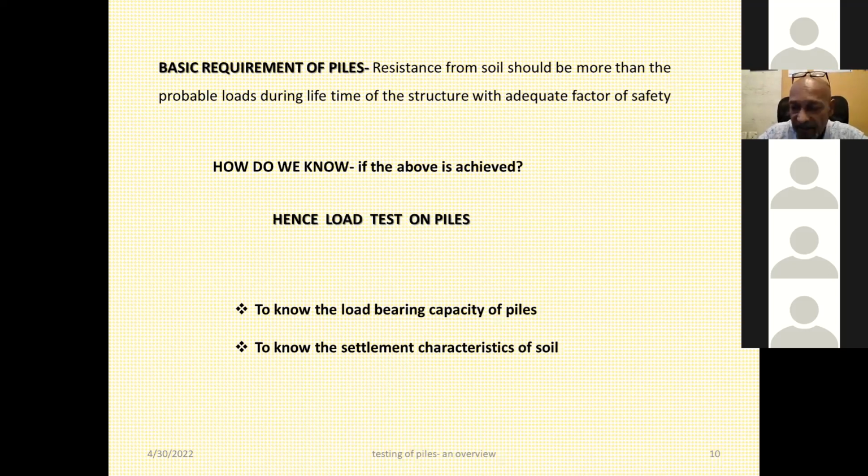Mr. Jain Kulkarni had shown a world famous building, the Leaning Tower of Pisa. We also have a Leaning Temple in Varanasi. And these are because of uneven settlement of the strata. Therefore, understanding the settlement characteristics of soil or the strata is very much required, especially when there are friction piles. That may not be so much required for the end bearing piles.